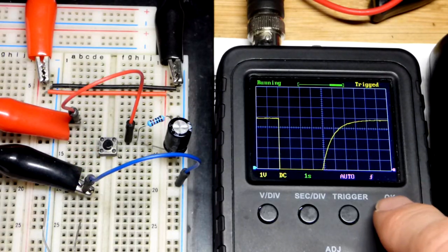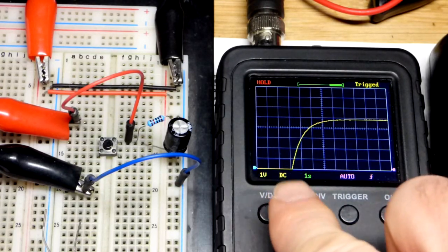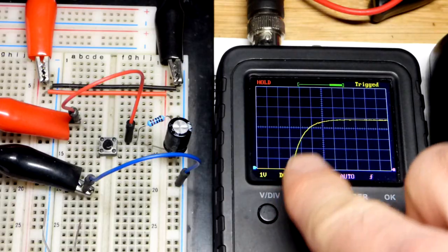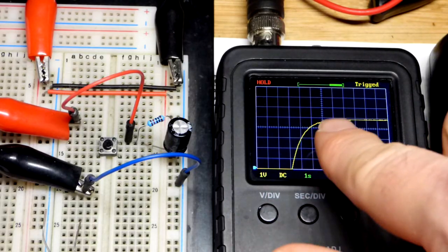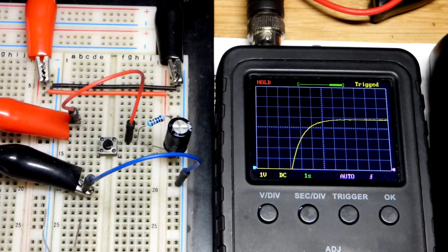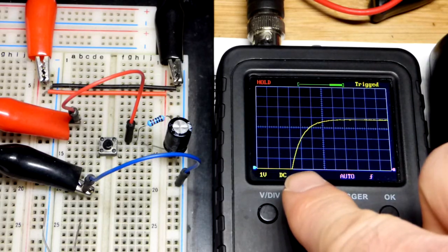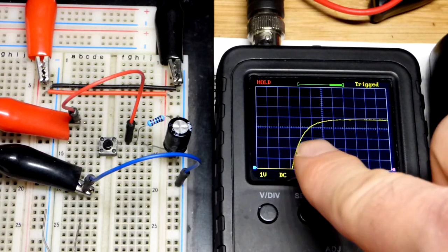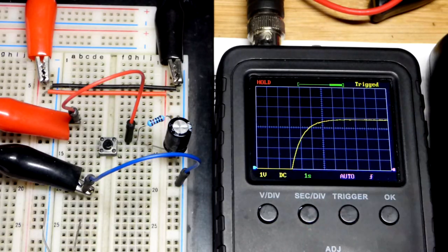And make sure I hit the right button. So I'm just going to try to stop right at any division, so it's off to the right a little bit, but you can see it's basically the same curve. About 3 volts in the first second, a little less than a volt and a half it looks like in the second, and so on. You got about 2/3 of the total supply voltage, or what's left of the difference right there. So in the beginning we got the total supply voltage, it's about 2/3 of that, and then about 2/3 of what remains, 2/3 of what remains, and so on.